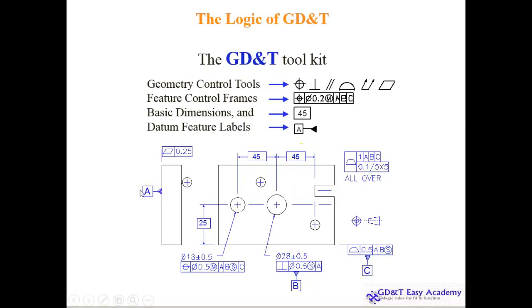Even though you allot the datums as flat planes, maybe with respect to the three different directions, XY, YZ and ZX, these are the flat reference, perfect reference, but after manufacturing parts cannot be perfect. So this datum, most of the people say that this is inside the part. No, this is inside your inspection instruments.